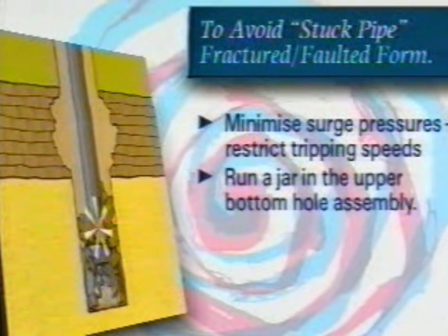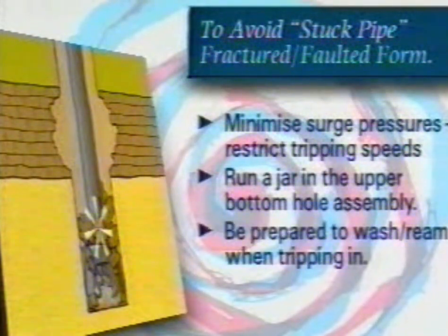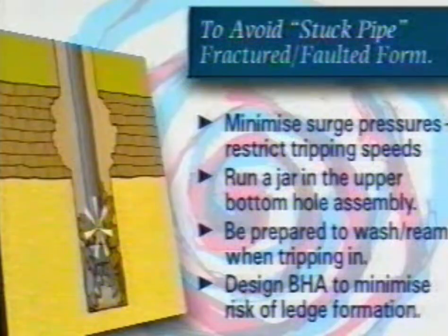Run a jar in the upper BHA. Be prepared to wash or ream when tripping in. Design the BHA to minimize the risk of ledge formation.